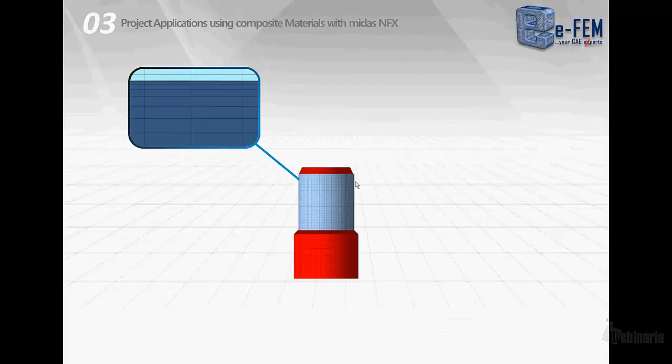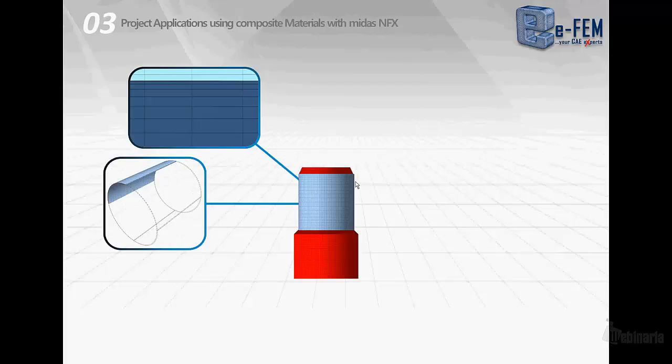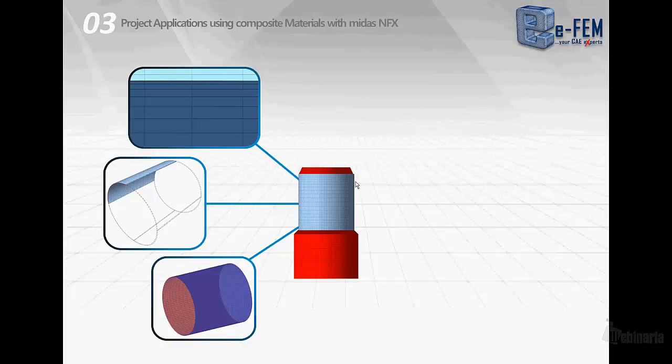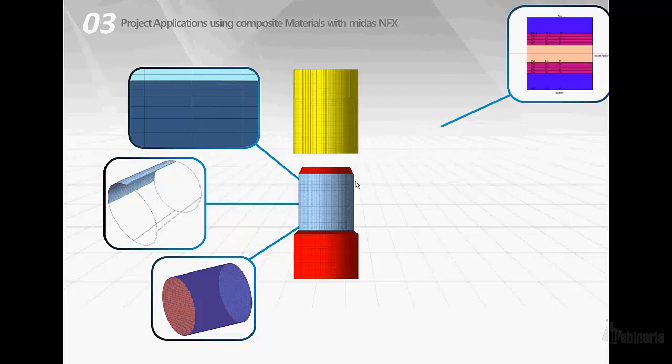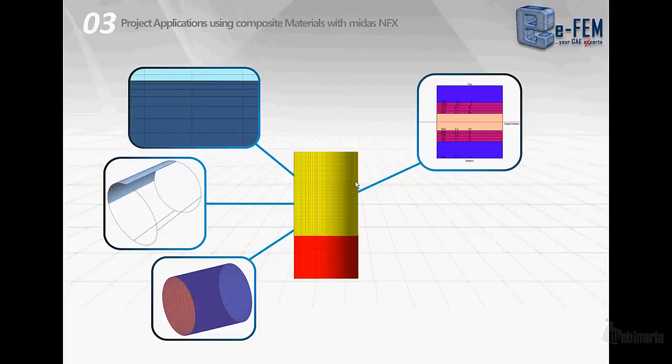The second model, as I told you, is a submodel of the bonded joint, an idealization of the joint. The model has been built manually, starting from a 2D mesh that has been revolved. The model is made of 3D elements, and good attention has been paid to the mesh size and local mesh refinement in order to have a good description of stresses. The glue has been discretized with 2 layers of 3D elements in order to have an accurate stress distribution, and a bonded contact has been used to link the glue with the aluminium and both with the composite part of the joint.